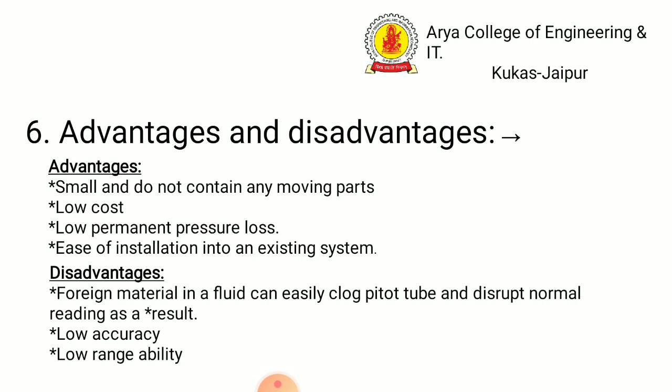The first advantage is that it is small and does not contain any moving parts. Second, low cost. Third, low permanent pressure loss. Next, it is easy to install into an existing system. Now the disadvantages. Foreign material in a fluid can easily clog the Pitot tube and distort normal readings as a result. Low accuracy and low rangeability.